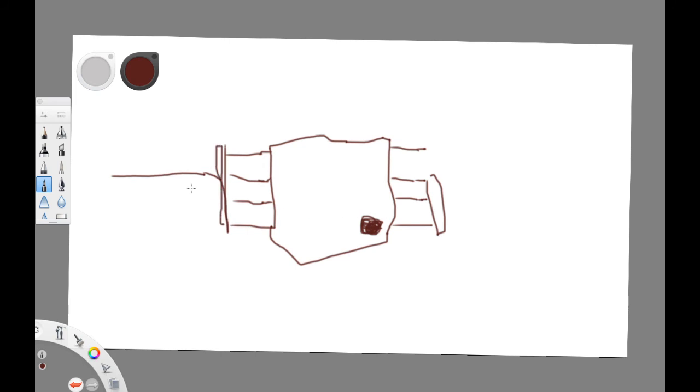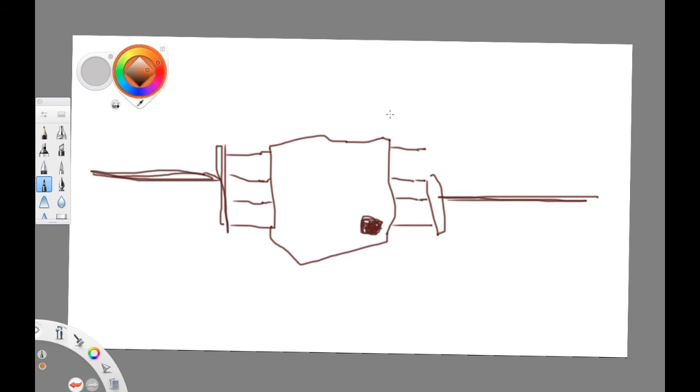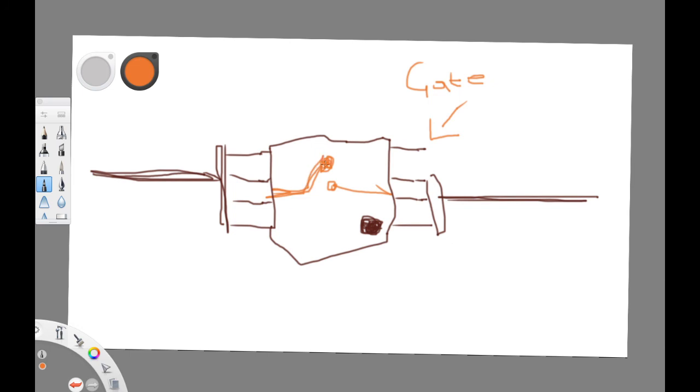In order for this thing to allow this 19 volts to pass on this side and go all over the board, this pin here, the 4th pin, is the gate. It acts like a switch, telling this guy to close. Let me draw it as a switch. Here I'm making an example. It's more like this, if you want to understand it.